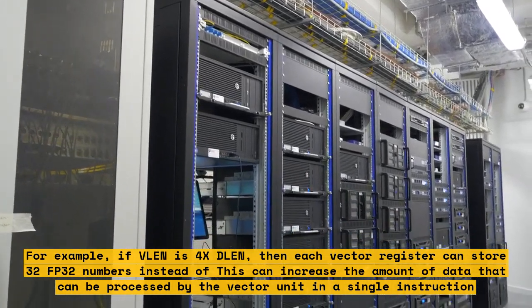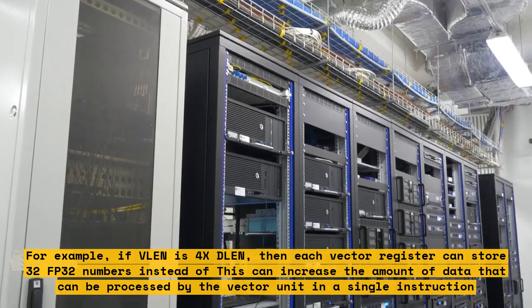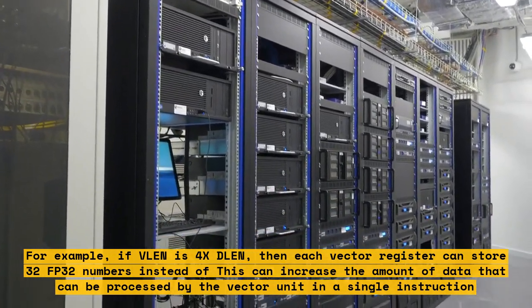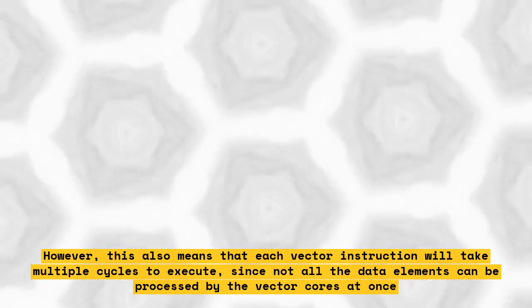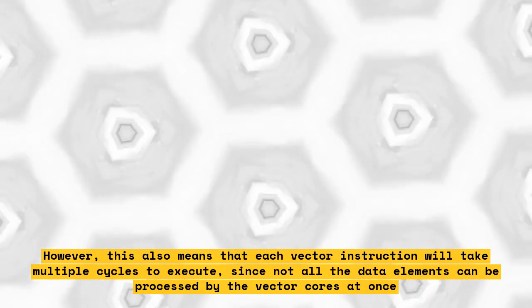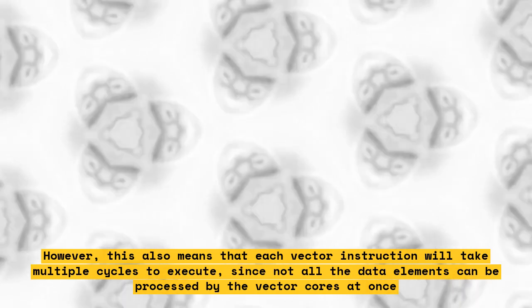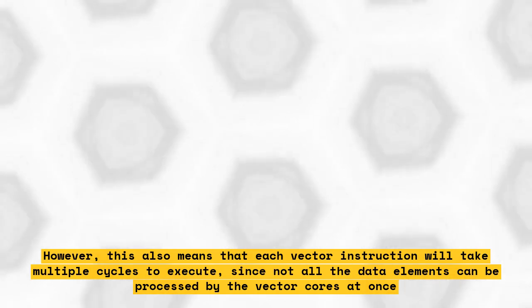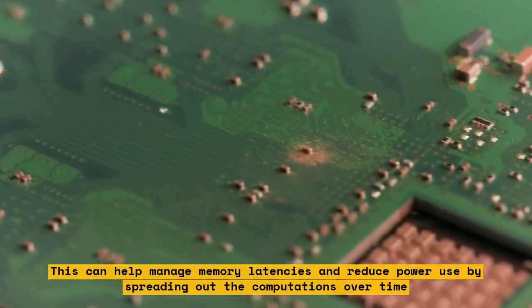This can increase the amount of data that can be processed by the vector unit in a single instruction. However, this also means that each vector instruction will take multiple cycles to execute, since not all the data elements can be processed by the vector cores at once. This can help manage memory latencies and reduce power use by spreading out the computations over time.